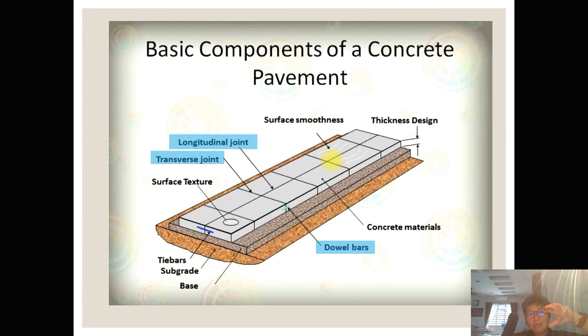The bottom one starts giving off heat, but the layer above prevents the heat from escaping, and then that layer sets and produces more heat. So the heat will accumulate and compound itself. Most likely the concrete, especially at the bottom, is going to be weak. Because the heat cannot be removed, funny chemical reactions come in, and the structural bonds of the concrete mass will not be as designed.